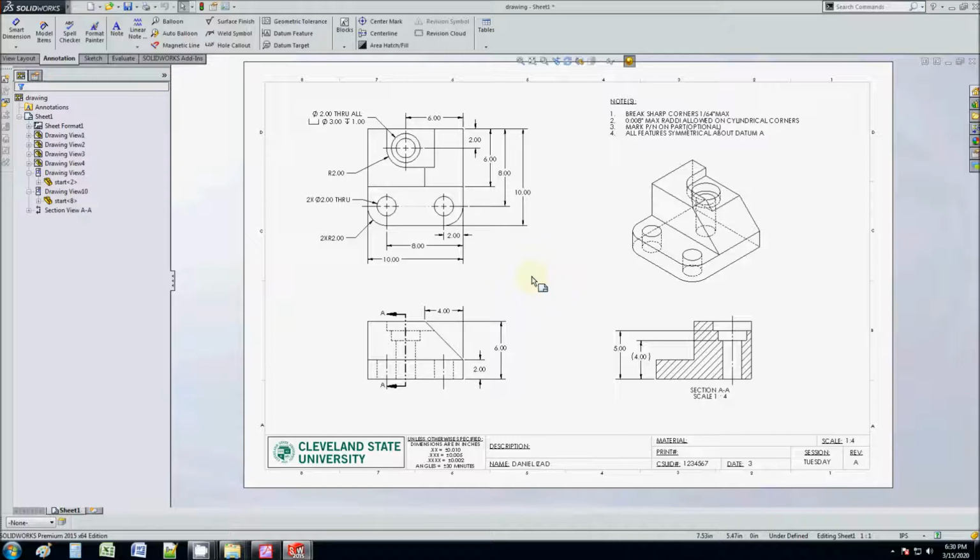So when you add material, you don't want that to be bound to the drawing. You want it to be bound to the model because it's just a better way to work. Let's say you have to update the material. You don't want to update 1,000 drawings because you'll forget, you'll make a mistake. But if you update the material on just the model, all the drawings are going to update.